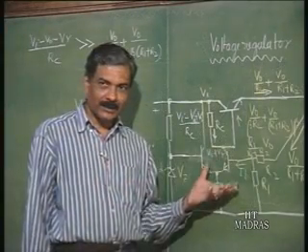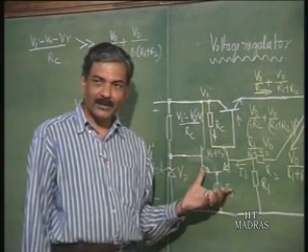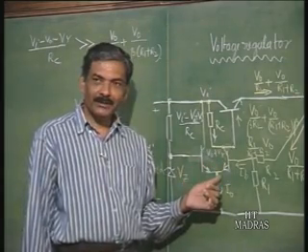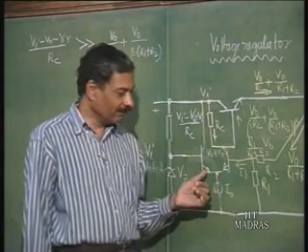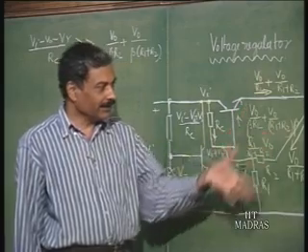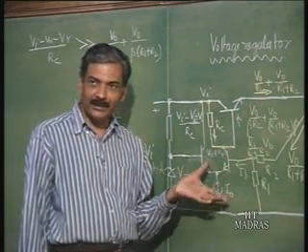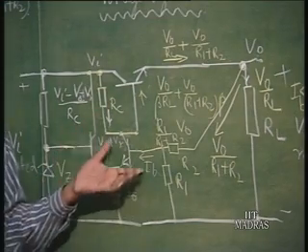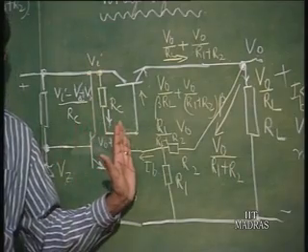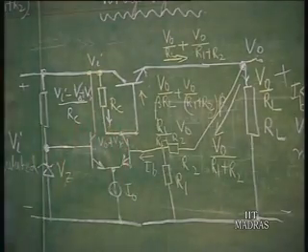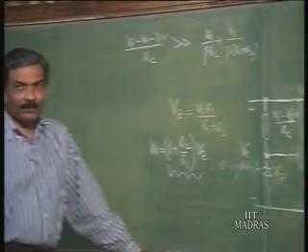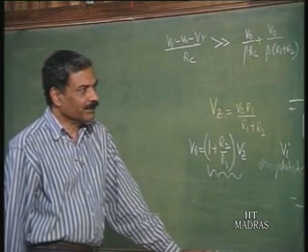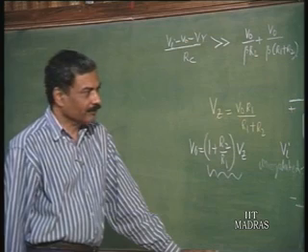So, all these things you have to remember, because it depends upon the operating point. The small signal definition of the equivalent circuit is based on the operating point, and it is not necessary that this should operate at all times with equal division of current here. So, this is a DC amplifier actually. Voltage regulator is using a DC amplifier for regulation purposes, and therefore, the operating point keeps on shifting as far as this is concerned. So, we will perhaps work out an example of this regulator and see for ourselves all the limitations that can come about in this circuit.